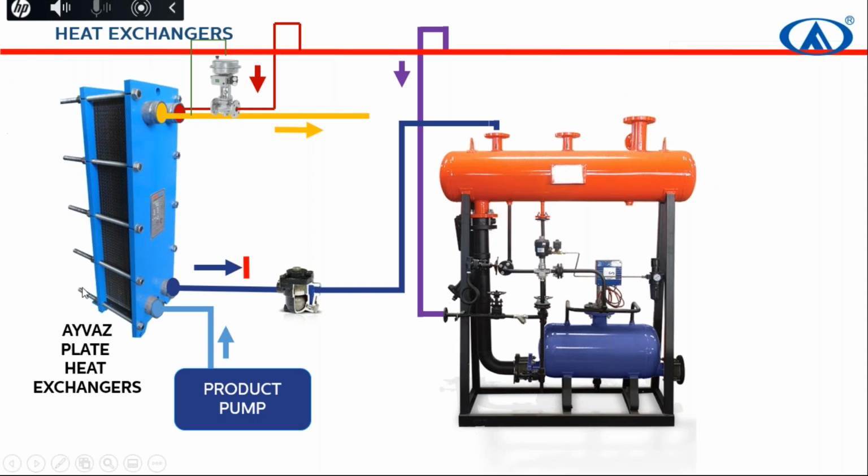If you have, for example in the food industry, more than 3 or 4 CIPs, cleaning in process, or pasteurization tanks, or if you have in the dyeing industry dye tanks, dryers, washing machines, etc., you can push all this condensate with a condensate transfer pump on a room basis.